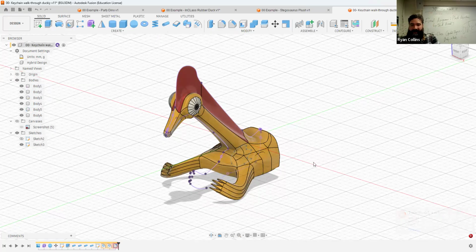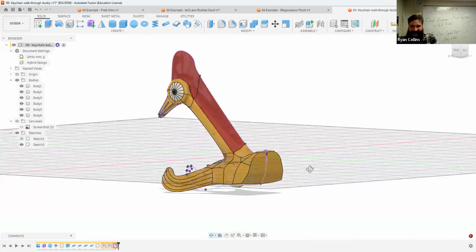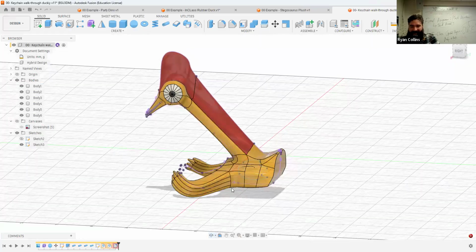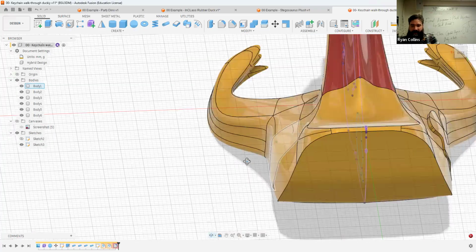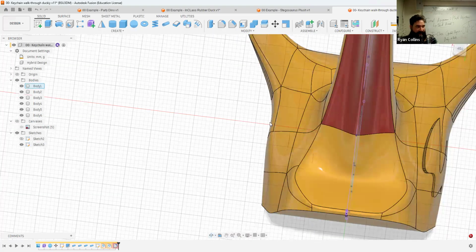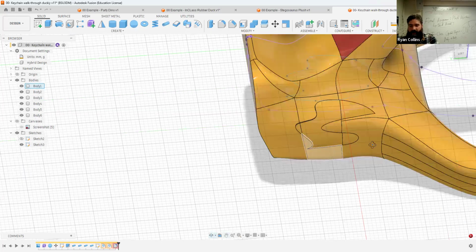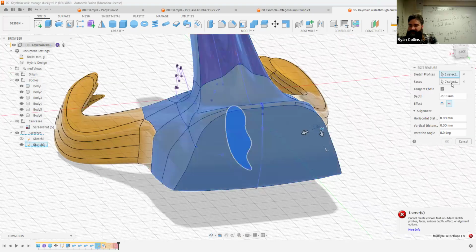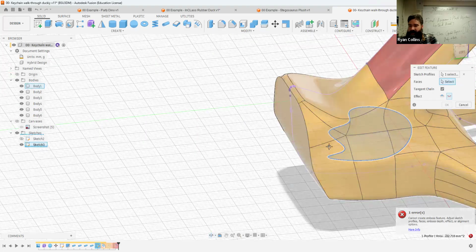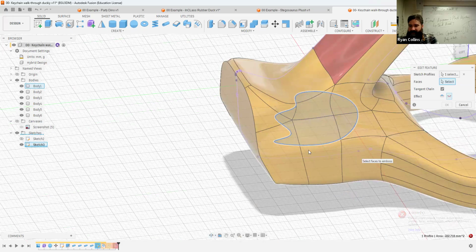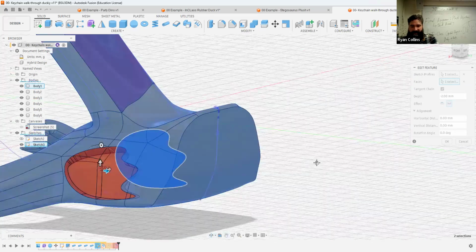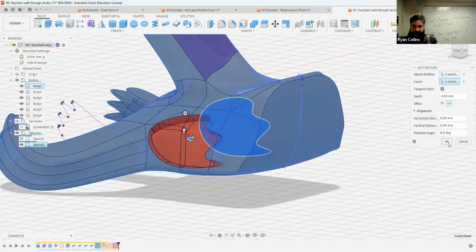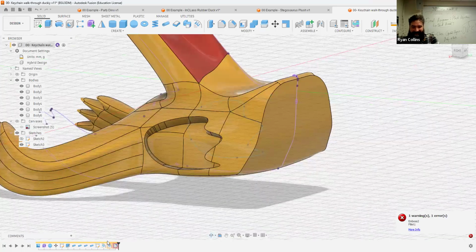That's okay. We can try to reapply. But this is actually one of the things I wanted to show. Oh, God, that's so much worse. That hand. The emboss doesn't work now because the surface is too complex. So obviously a way around this is to go back and change things around. We could also try to reapply. Let's try this. Sometimes it works, sometimes it will not. I'm now selecting the faces. And of course, now it's applying it to the opposing side, but it looks like it'll work. Yeah, it's got dino damage now.